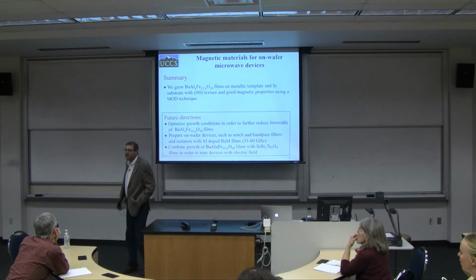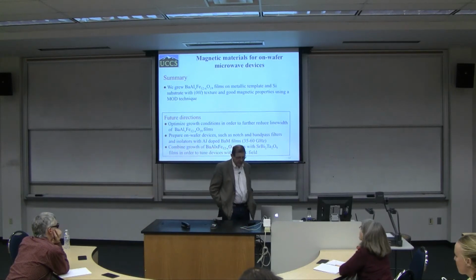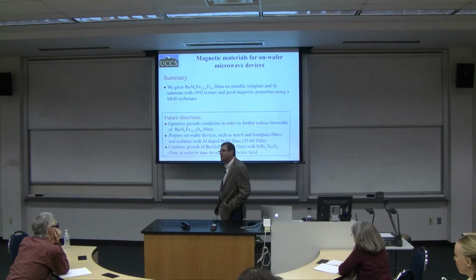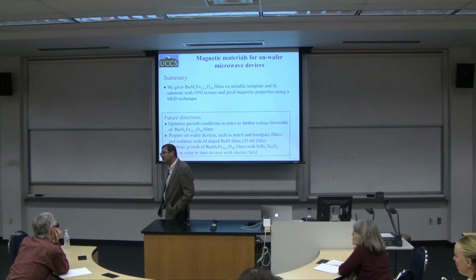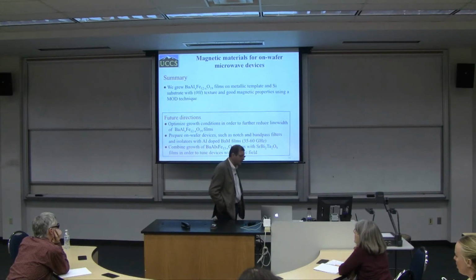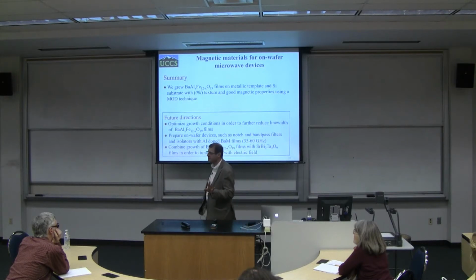Platinum for two reasons. We are growing these films, and we are annealing them in a rapid thermal annealing unit up to 1000 degrees. So if you put a different metal than platinum, you're going to anneal it. Sorry, you're going to oxidize it instantaneously. So this is the reason why platinum. Now, from the point of view of cost, this is nothing.